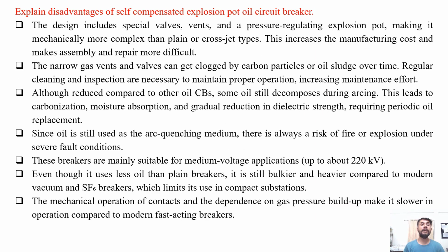Explain the disadvantages of the self-compensated explosion pot oil circuit breaker. The design includes special valves, vents and a pressure regulating explosion pot, making it mechanically more complex than plain or cross-jet types of oil circuit breaker. This increases the manufacturing cost and makes assembly and repair more difficult.